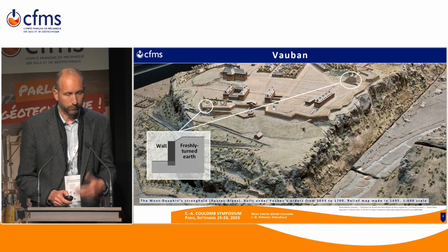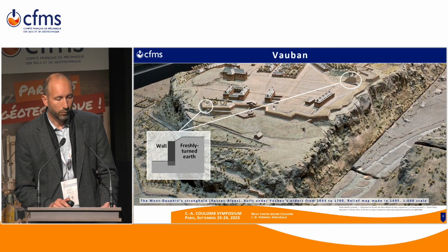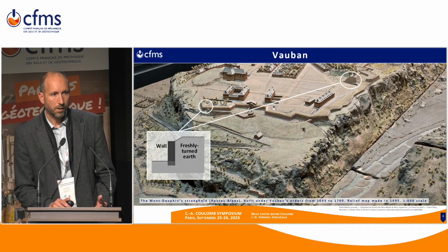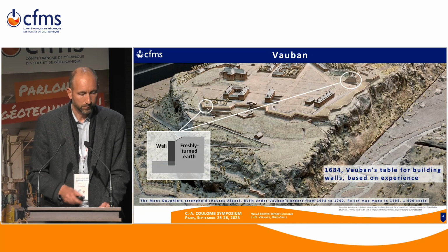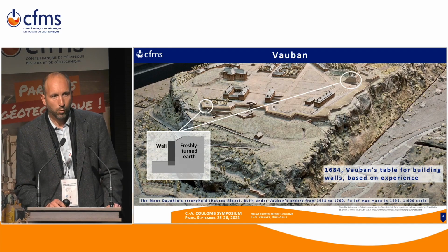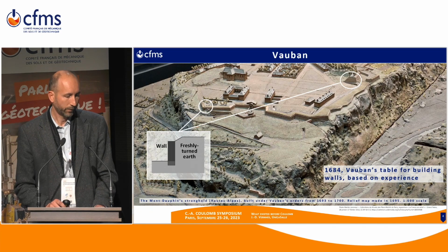Those retaining walls were quite vulnerable, and this obliged Vauban to give all the military engineer community of his time a table to build those retaining walls with dimensions that would be controlled. Given the height of the retaining wall, this table would fix its average width.